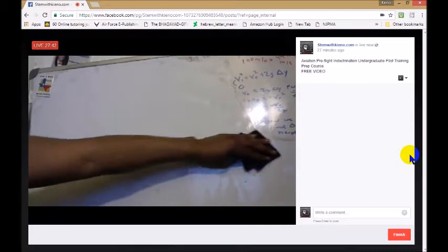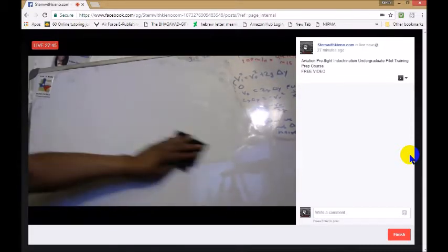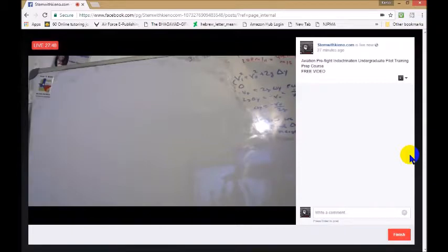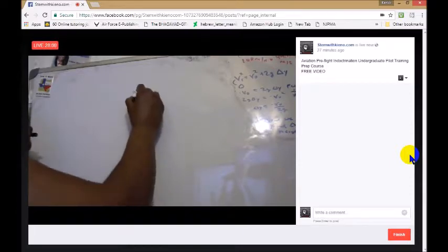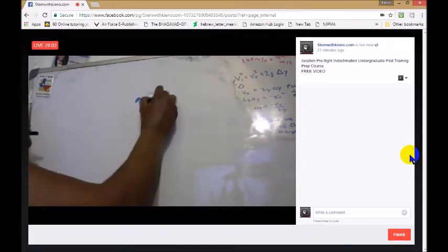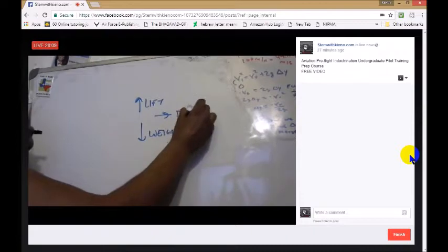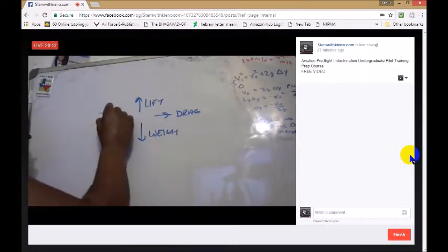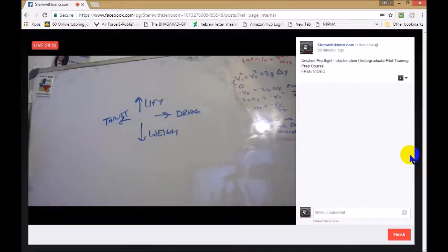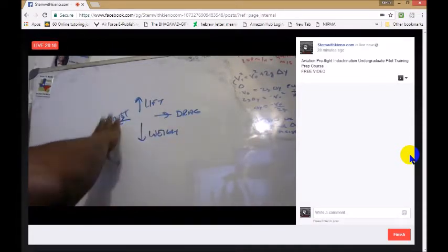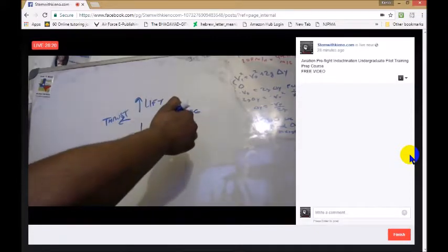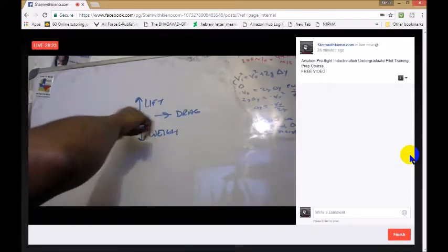Okay. The next topic that you will need to be familiar with in flight training is a phenomenon called ground effect. Ground effect significantly reduces induced drag and increases effective lift. So what does that mean? That means out of our four basic forces of flight, we have lift being generated. We have weight, just caused by a gravitational pull. We have drag, and we have thrust being produced. All right, so the thrust is being produced. Now, in unaccelerated flight, where you're just at a constant airspeed, the lift equals weight and the thrust equals drag.